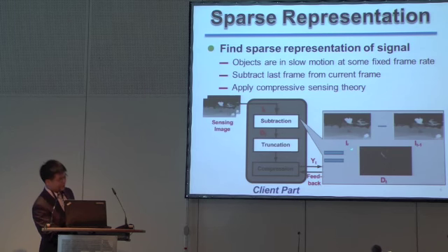Then this is a sparse signal. To enhance the sparsity of this signal, we truncate small values. As there is a lot of noise in every sequence, we truncate to make the compressive sensing recovery more robust.